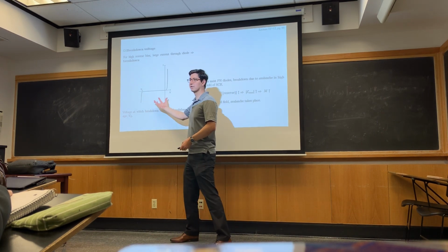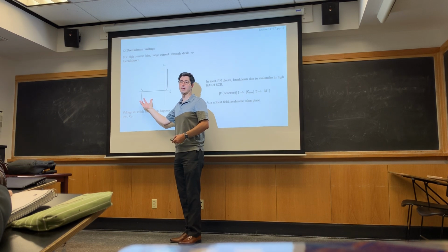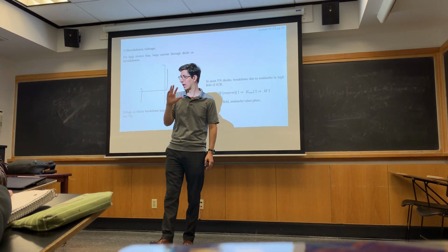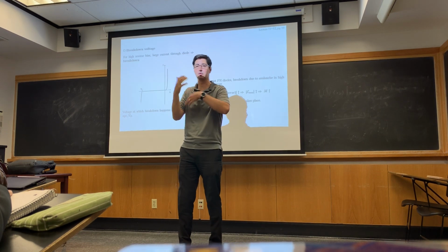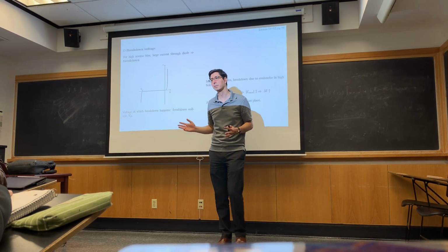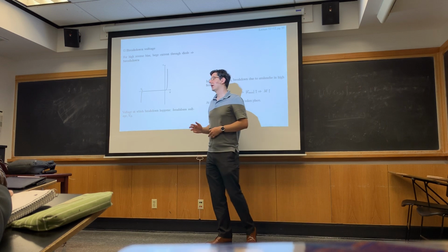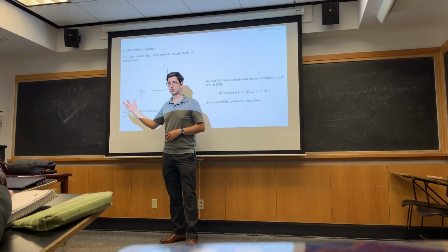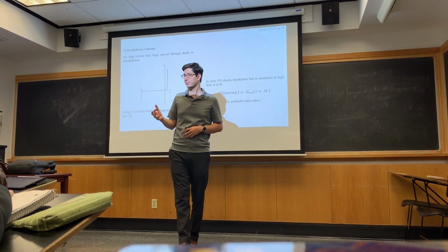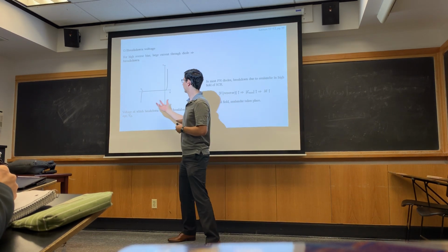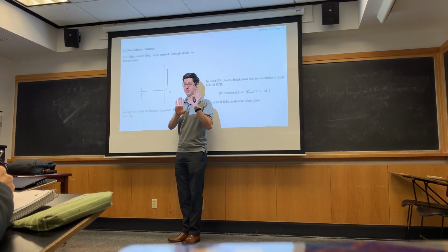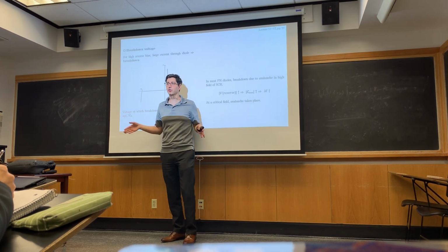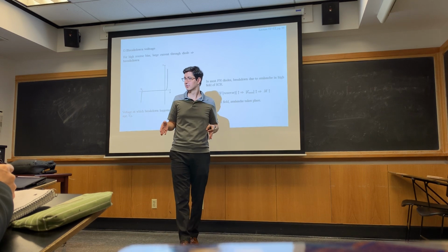So what if I took this device, right? Let's say it was rated for 1 amp. That was the max current that this diode was rated at. That's what it was designed to handle without burning up. Okay? If I put a 1 ohm resistor in series with it, or it depends on, let me back away from that statement a second. If I know what my max voltage will be, right?